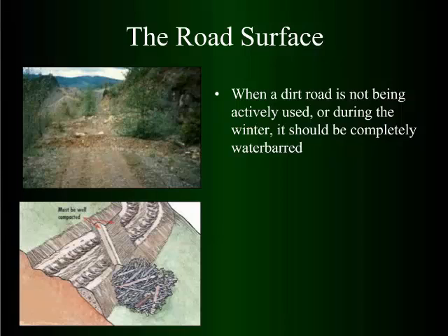Okay, on the road surface here, this is a water bar that's obviously put in to close the road. That does protect the road surface, but then again, I guess you're protecting something you're not using anymore. The main thing, I guess, would be that you're keeping the erosion down. This example shows that it's notched into the subgrade deeply enough that if somebody were to drive through this thing, it would probably still function. An example where they're using some organic material for energy dissipation and trap the sediment.